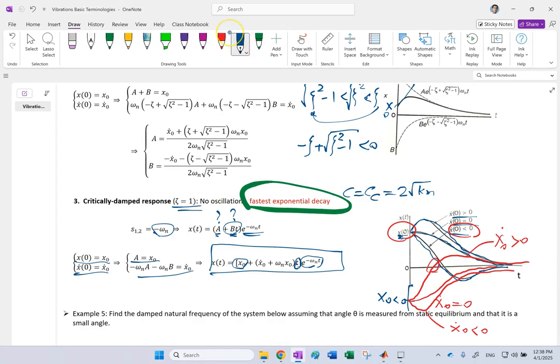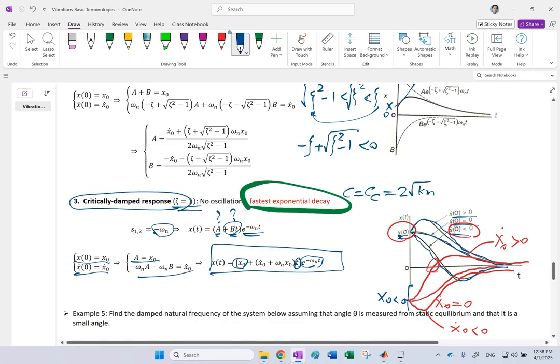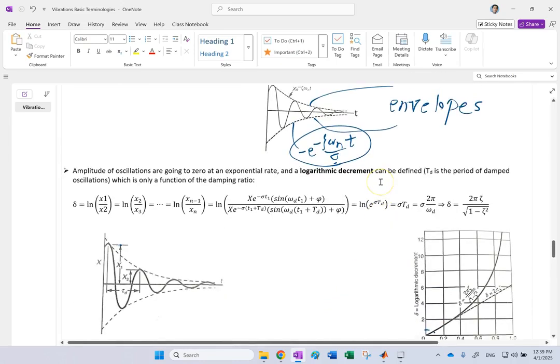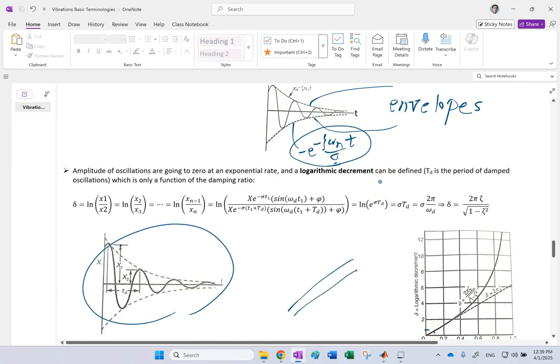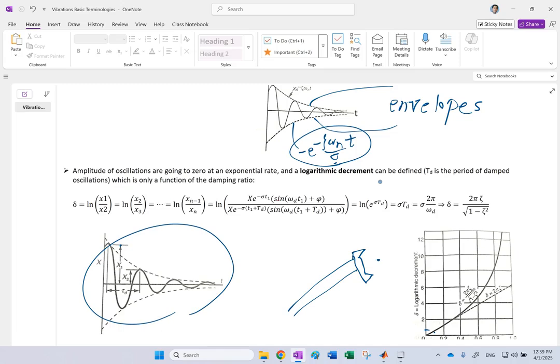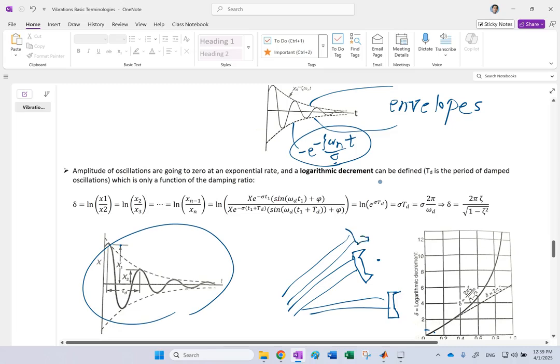And in robotic systems, when they want to control joints, they typically pick their PID controller gains so the response of each joint is a critically damped response rather than an overdamped response. And in robotics, we never really want an underdamped response. We don't want our arm to reach a position and then do a couple of oscillations around it before settling down at that joint angle, right?